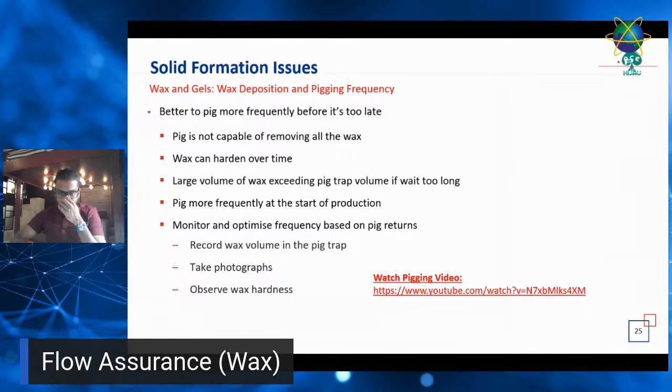Another thing you have to be aware of is that if you start pigging frequently, there will also be instability in flow in your production, because you will incur operationally induced slugging in your flow line as you start pushing your fluid to your processing facility. That's when you may also flood your separators, and there will be a fluctuation of production and water instability at the same time.